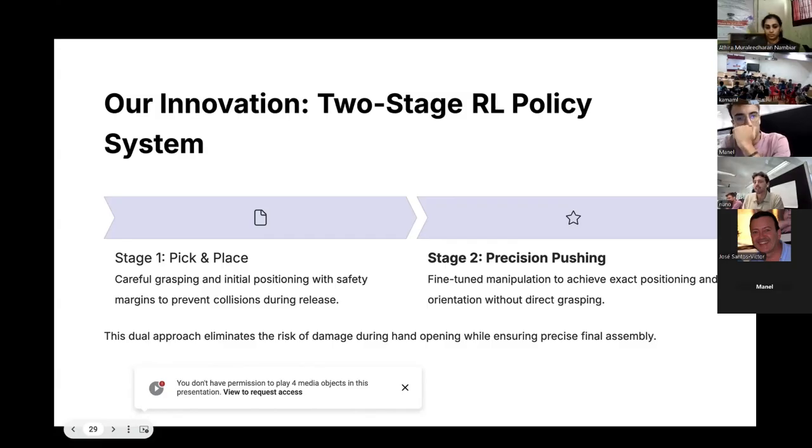But the robot has limitations. When it has to release the object, it has to have space to open the hand and safely step away from the table. So we cannot place objects too close to each other, because this would lead to accidental touches and possible scratches to the fragments that are already in the completed location.